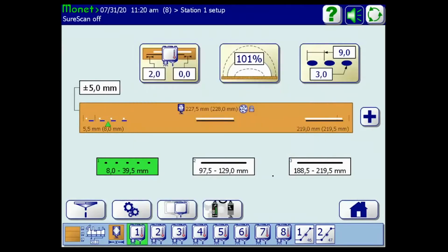So is that gap in the size specifically for this pack? Can I change a different gap and glue pulse time frame on a separate pack, like pack A versus pack P, or is that a global setting? So it's a setting per glue valve. For this glue station number 1, putting down these 3 glue lines, I can have one programmed spot gap and size for all glue events from this glue gun. So each glue gun has its individual spot setting. Glue gun 2 can have different size dots and spacing from glue gun 1, from glue gun 3, and so on and so forth. So it's specific to the glue valve itself.